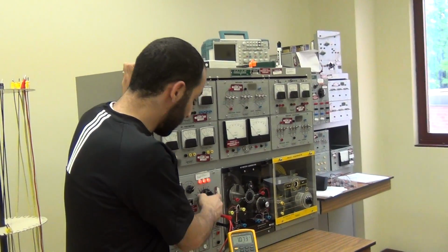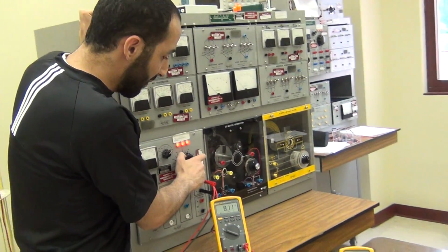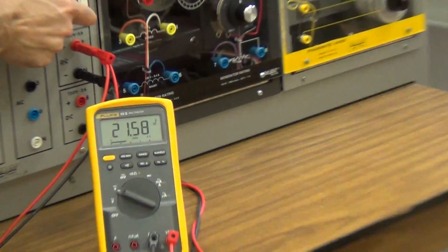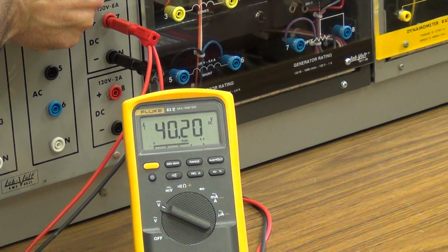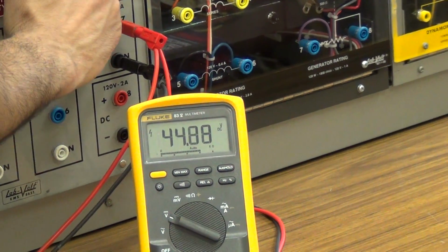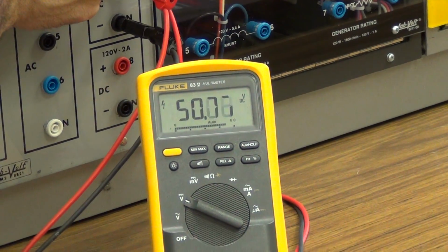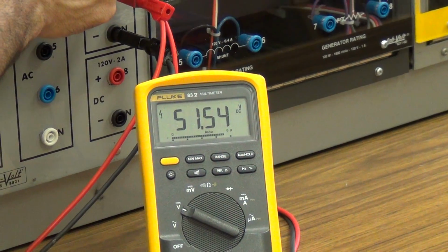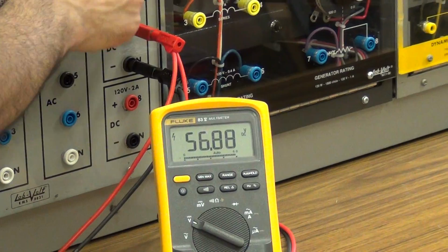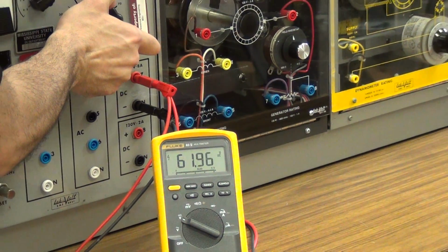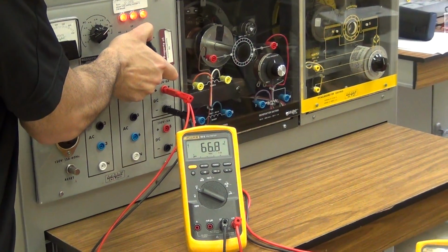Okay, this is the DC voltage source. We need to increase the DC voltage source to some value around 70. This 70 volts will be converted at the AC side to around 40 when we have a modulation index of one, but we will do this experiment for a 0.8 modulation index, so we have 0.8 of 40.